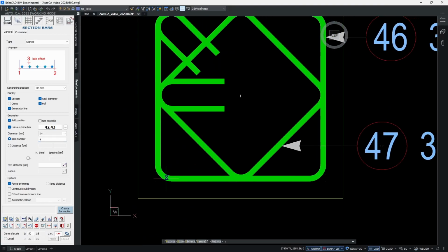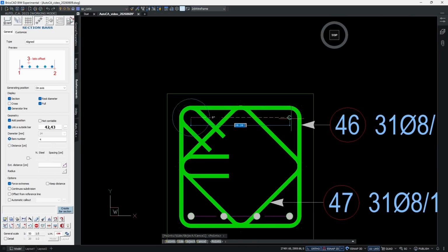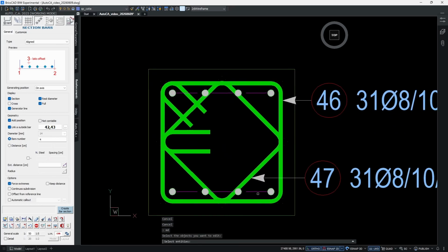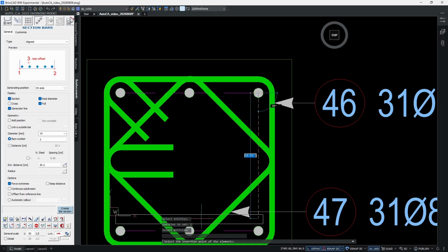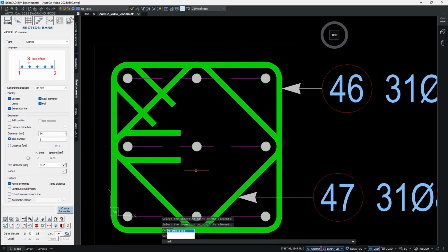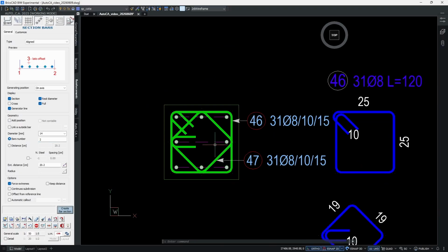Click on the button and select position for them here and here. And I said it wrong because we only need 3 bars on each position. Okay, so 3 bars on each side. That means that we need 2 more. And we can do that by copying this distribution. Copy it here and change the parameters back to 2 bars and add modification.